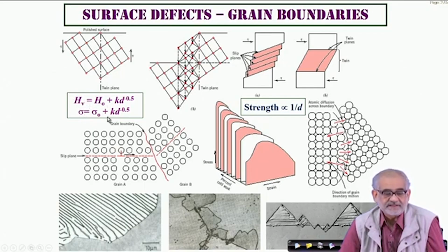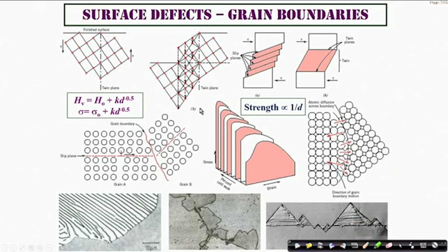So either way, this mechanical strength increases as the size of the crystallite, or so-called the grain size, decreases. And this is the famous Hall-Petch relationship, which many of you probably already know, which simply says that the smaller the grain size, the greater the strength of the material, and that strengthening arises purely because of the barrier posed by these boundaries to dislocation movement.